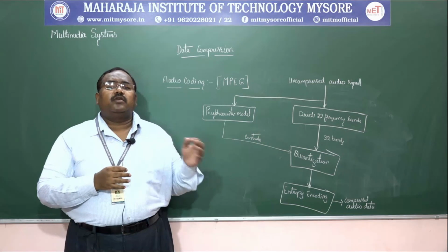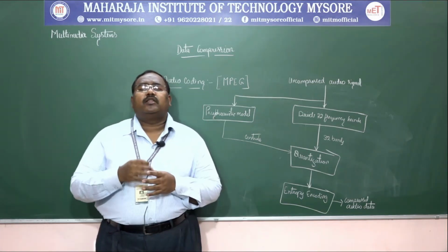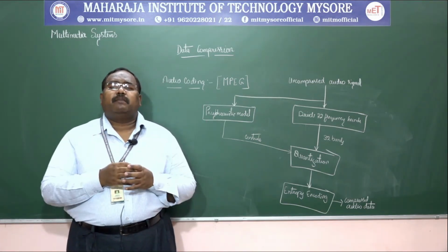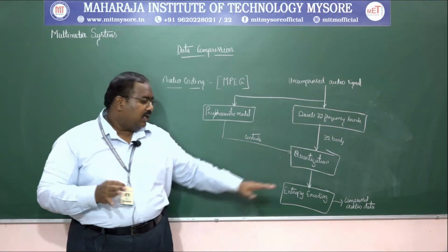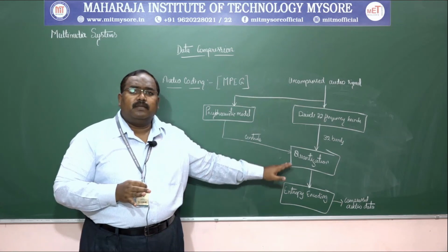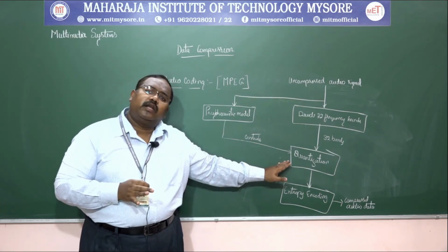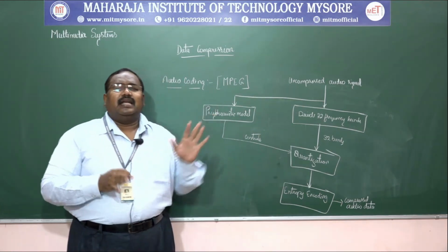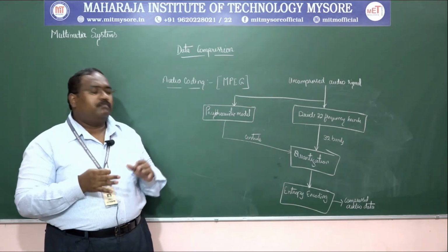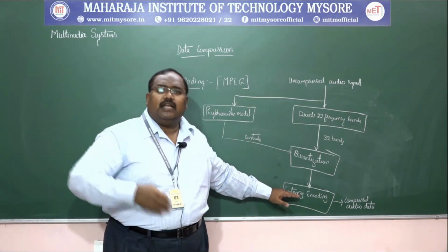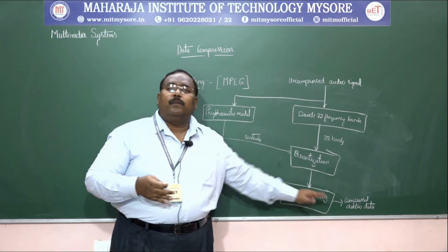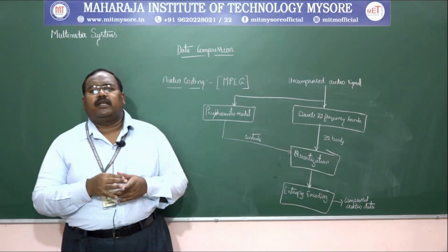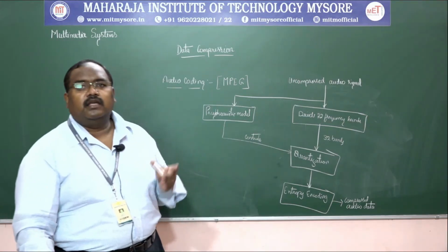No need to worry. In the first and the second layer, the appropriately quantized spectrum components are simply pulse code modulation, that is PCM, encoded. In the third layer, if you need any additional performance, you can use entropy encoding, that is Huffman coding and other things.